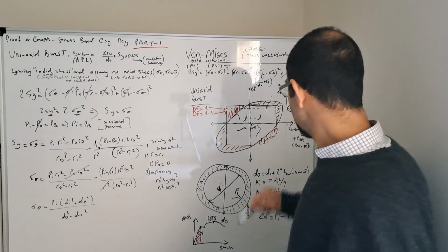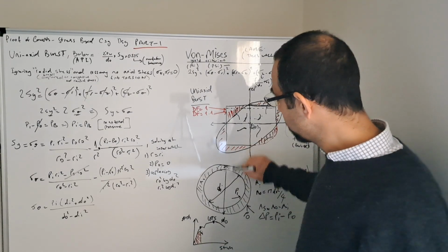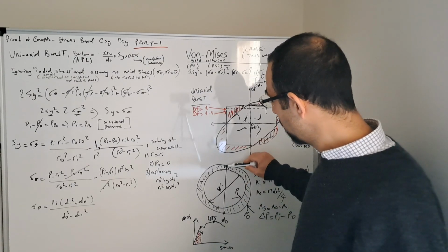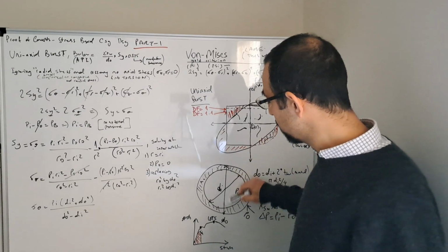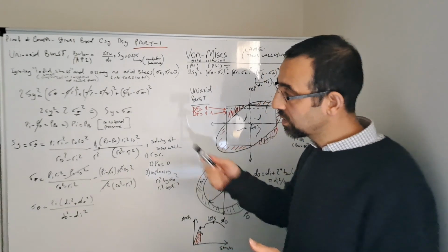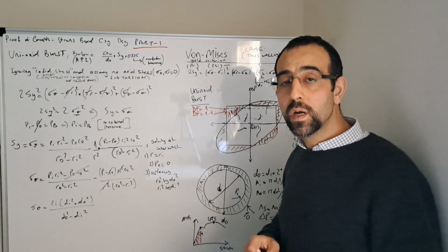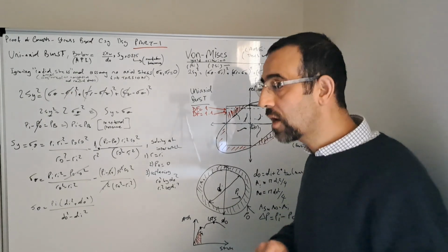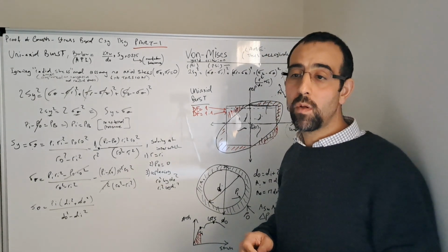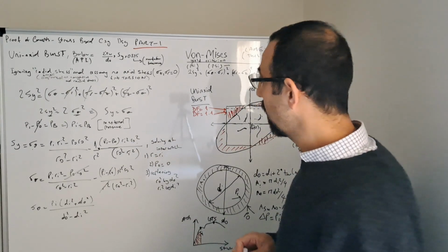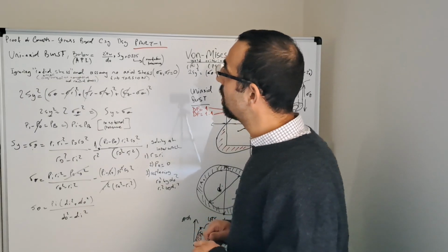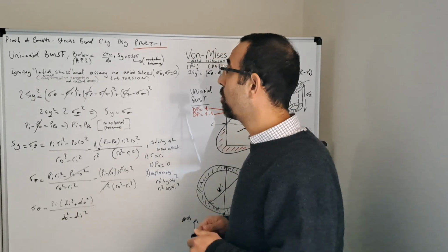As I mentioned here, the wall thickness is quite important. When we say the outer diameter, it is the difference between the outer diameter and the inner diameter. When you look at the book values, for example the data handbook, the green book, you will see all the wall thicknesses are nominal, and on the spec sheets they also have the nominal wall thicknesses. Okay, so let's look at the burst equation, which is a Barlow.